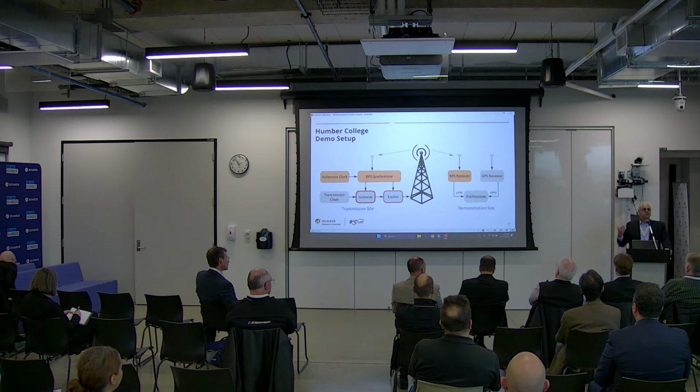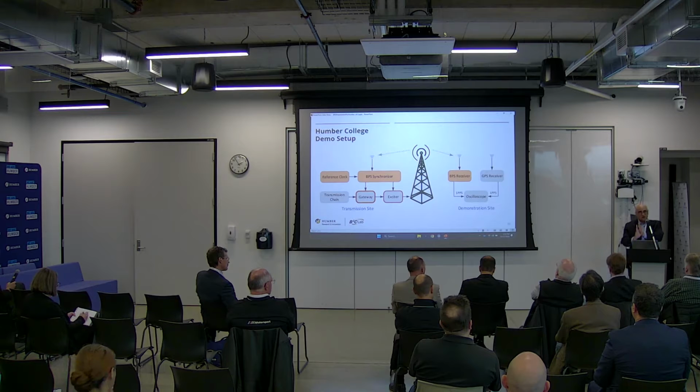Then to compare it with GPS, we have a GPS receiver, and we also take its 1 PPS signal and put it on a scope. We're triggering on the GPS signal and letting the other signal run. And we see that this BPS pulse is within less than 25 nanosecond of the GPS 1 PPS. 25 nanosecond. And we don't even have a line of sight. And the transmit tower, as I heard, is only 20 feet tall. And it must be low power. It still works.